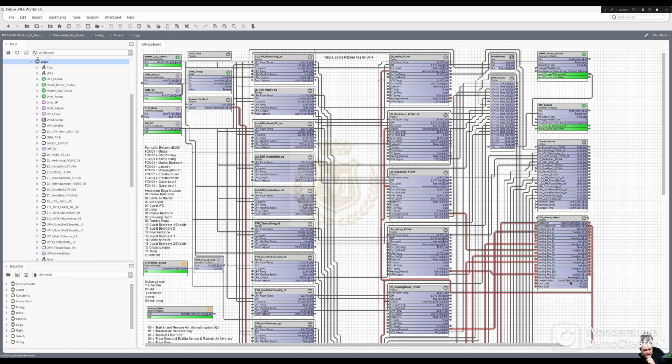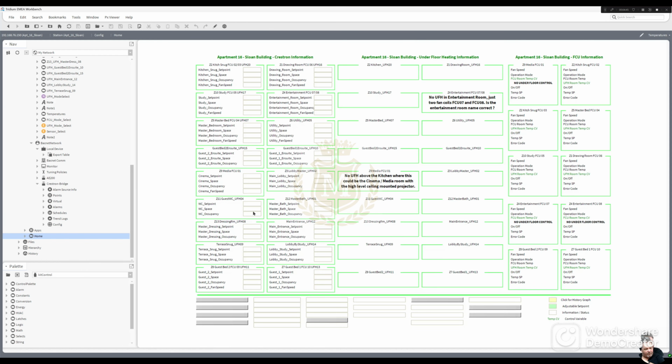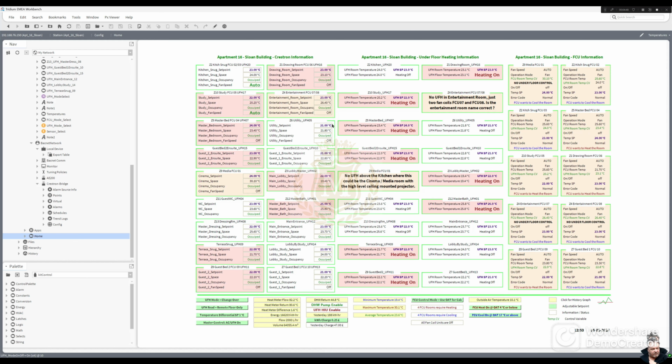Now we've only got one outdoor unit, so we can either all do heating or we can all do cooling. We can't do both. Currently there's 4 units want cooling, 4 units want heating in the rooms, so it's half and half at the moment. So it'd probably be better to work on outside air temperature in this scenario. And if I look at the graphic, which is just a graphic for me, it's not for the client, you can see that the outside air temperature is 10.1.